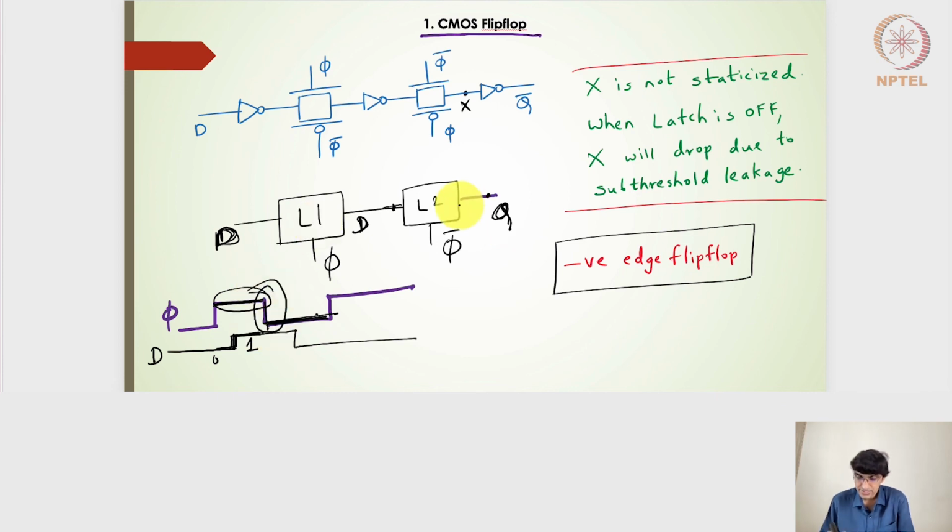So this works like a flip-flop, because a flip-flop is operating only on the clock edges, right? To use the latch design and derive the flip-flop design is very simple. We use the very basic CMOS latch design, where we have an inverter here and an inverter here, inverter here and inverter here. The outputs of the latch design help in making the circuit more insensitive to the input and output noise. And we have the transmission gates here, which are going to pass the input to the output based on the clock level.